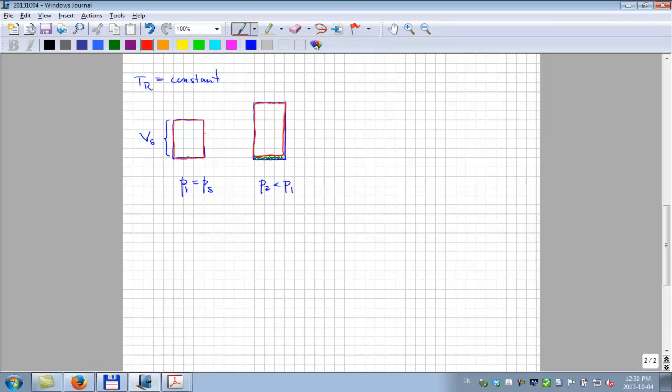It's a gas that is what we call leaner. It's a leaner gas because lean and rich is referring to money, okay, and or C5 plus content, which is the same as money, because you remember the factor of 22, more valuable sold as an oil than sold as a gas. So if we took this first gas to the surface, we might get 200 barrels of oil. But if we take this second gas to the surface, we're going to get 160 barrels per cubic meter of what we take out.